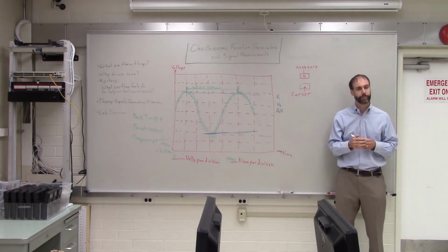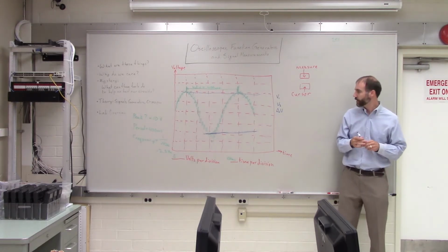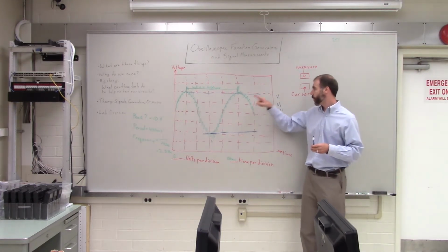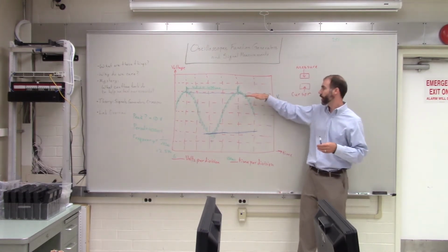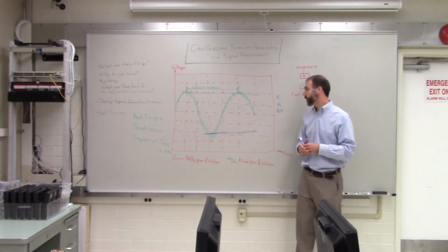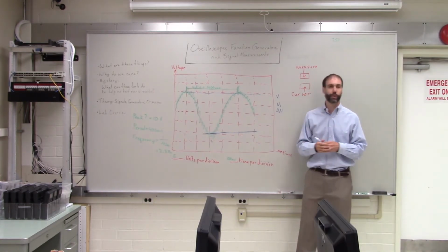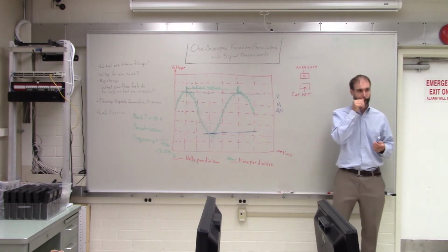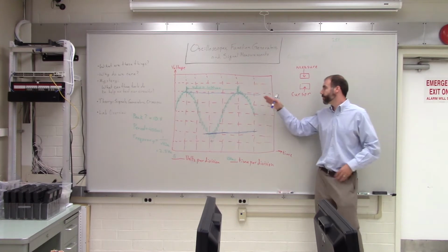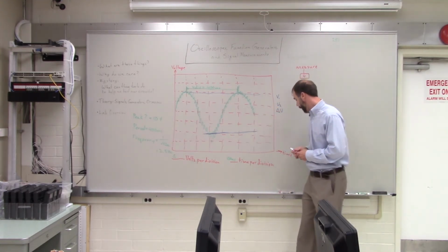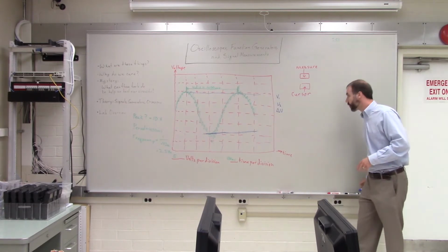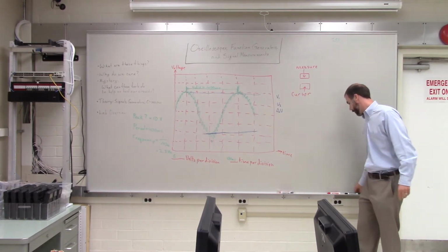So you probably want to use something like this when you have a bunch of noise, like that picture. Exactly. When the measure button is getting confused and giving you weird numbers, then you can try the cursors, and you might get more accurate measurements that way. So you can have horizontal cursors like that. You can also have vertical cursors.